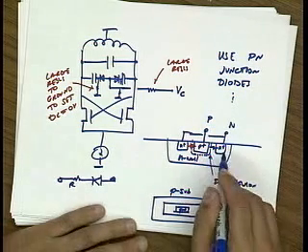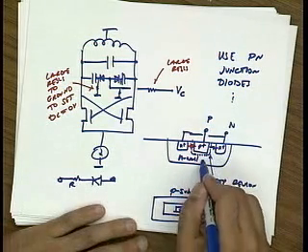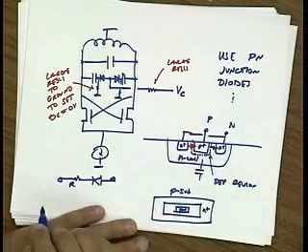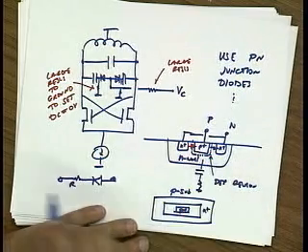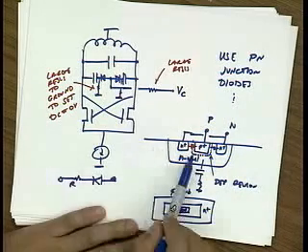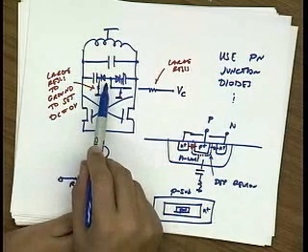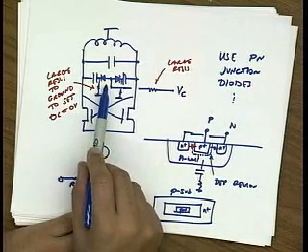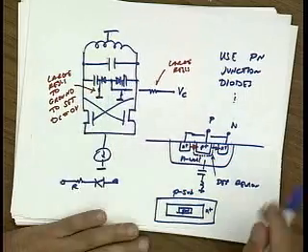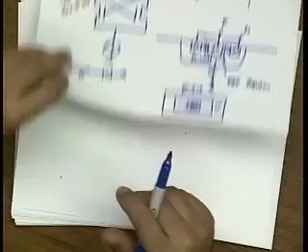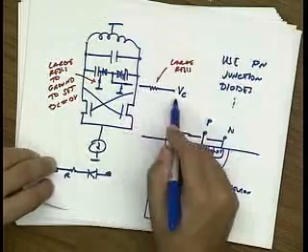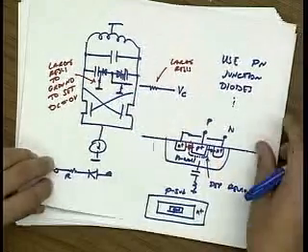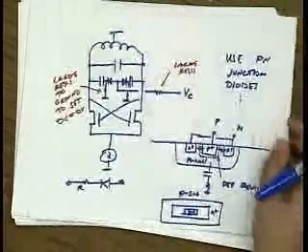You can see that the N node here is dirty because the N node has this well capacitance to substrate. So what I'd like to do is put the N point at the virtual ground, and that changes the way you would bias this. We talked about this already, so I won't go into the details. I think you guys remember. All I have to do is ground this side and connect this to VC, and I can have a nice controlled varactor.